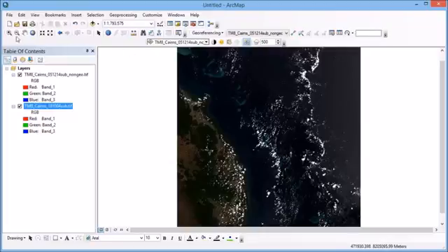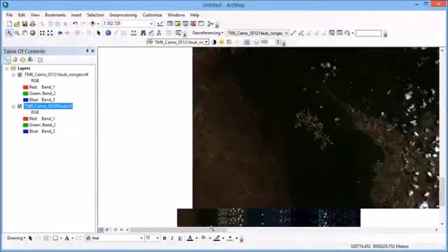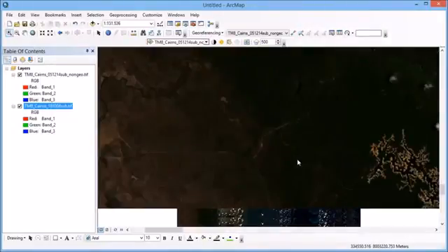So the first one that I'm going to pick, I know, is down in this bottom left-hand corner here. So I've found a point. This particular road intersection is what I'm going to start with. So in the georeferencing toolbar, I click my add control points little tool here. So once I click that once, I click on that point that I've found in my non-georeferenced image.